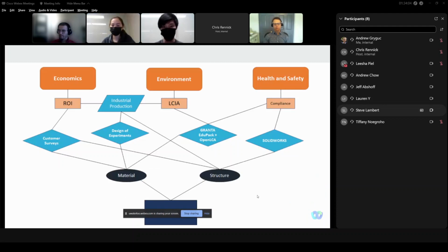And so at the onset of our problem statement, we require a 6-pack ring, or otherwise referred to as a yoke, that performs to the same or better degree than what is currently available. In addition to our final design, we require that the selection of not only a recyclable material be chosen that can easily be processed in the waste stream, but also a geometry that will not cause processing complications.